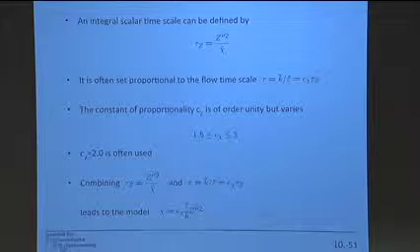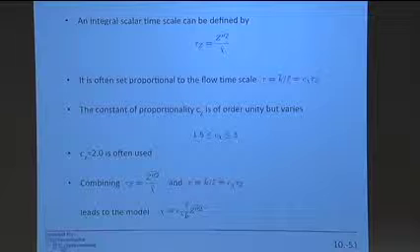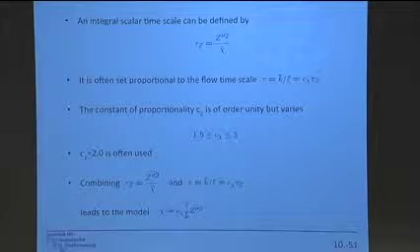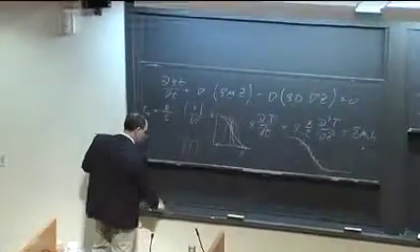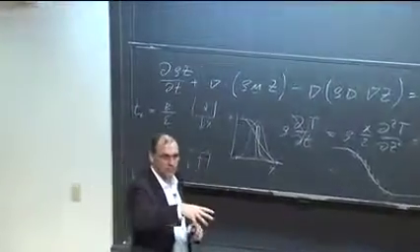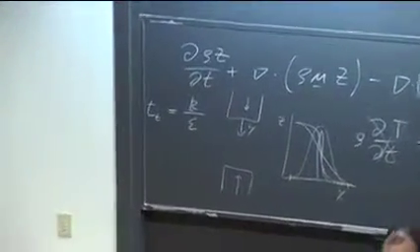And the model for the dissipation rate comes from a time scale argument. The argument is that we said earlier, the integral time scale of the turbulence can be written like this, is k divided by epsilon. Okay, the kinetic energy divided by its dissipation rate.